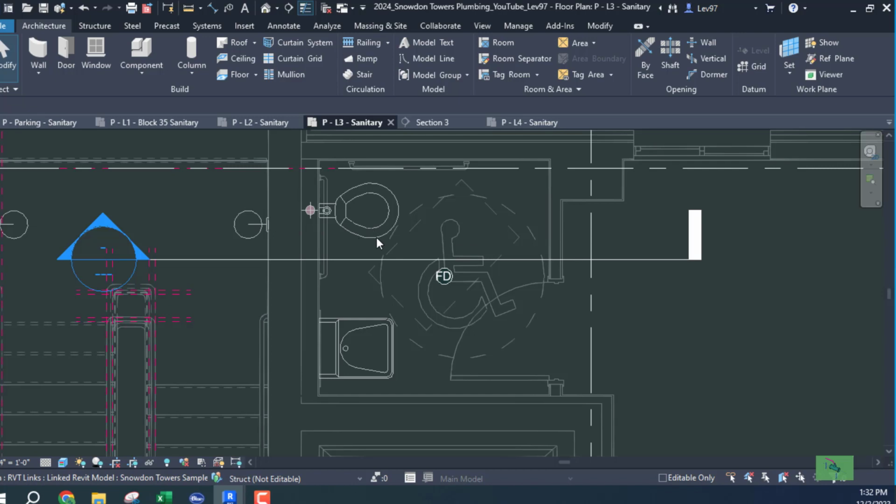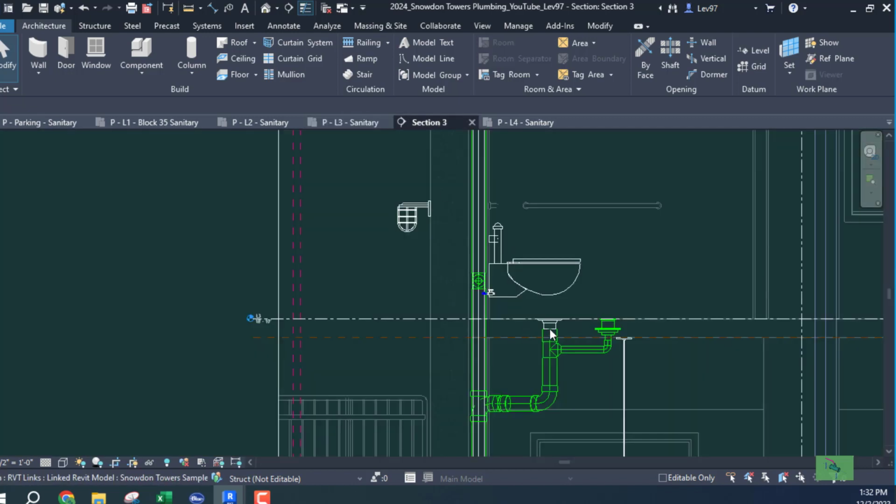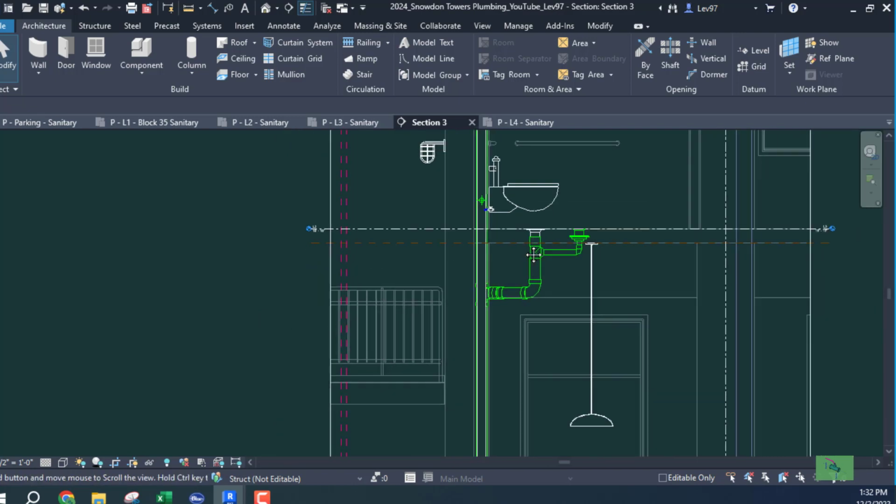Okay. So there was a little bit of confusion, it looks like, between the plumbing and what they were trying to do in terms of how it was going to be drained. Because they are using it as if it was a floor-mounted toilet instead of a wall-mounted one. Because the wall-mounted is going to go back into the wall. A floor-mounted toilet is going to go down into the floor and then drain, as you can see.